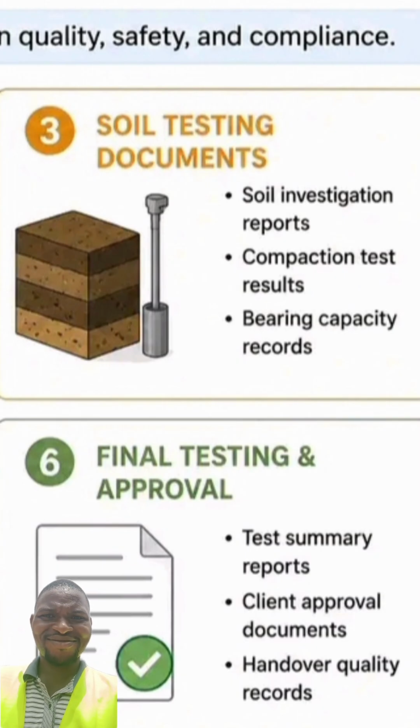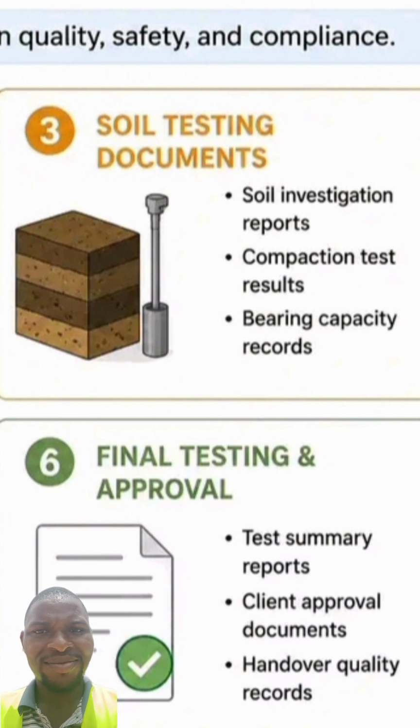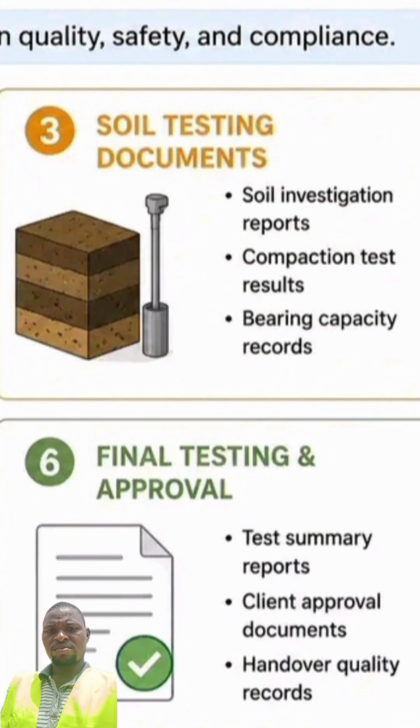Then we have the bearing capacity records. So maybe you did your bearing capacity test. You understand? That is to know the soil bearing capacity. All these records are very, very important, because your soil bearing capacity will tell you if the structure will be able to hold. It tells you the type of foundation you are going to require for your building. So it is a very, very important test, and it is good you have the records of all these tests.